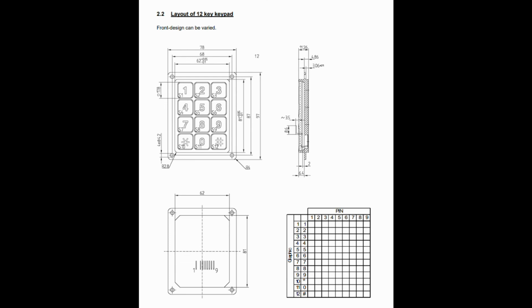So what's a placeholder? It is a piece of geometry, a piece of CAD that is not intended to be an exact replica, but to have the critical dimensions required. For example, the outside perimeter and the mounting holes are required. You may also want the thickness. You can get fancy. You can put some numbers on it. You could skin it. There's a lot of things you could do, but none of it's really required past the mounting holes and the absolute geometric bounding. Okay. Once you import these parts, I want you to obviously move them to their own layers.